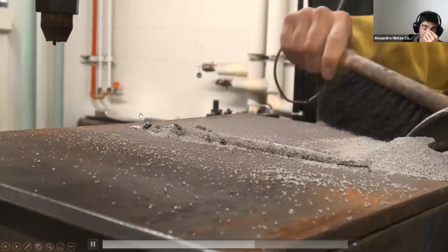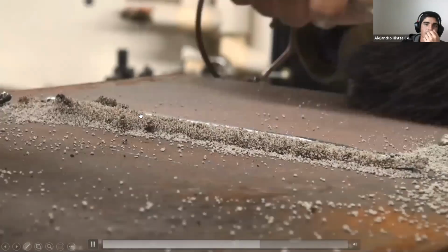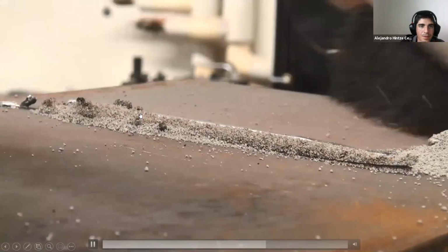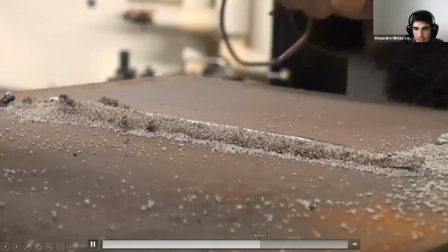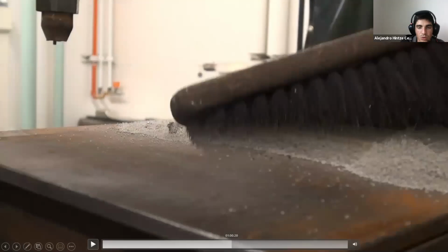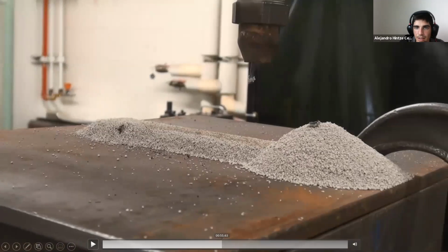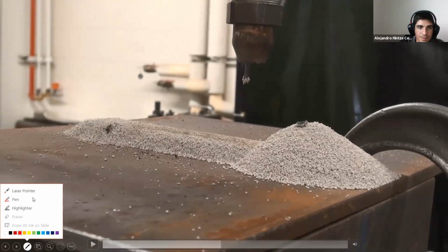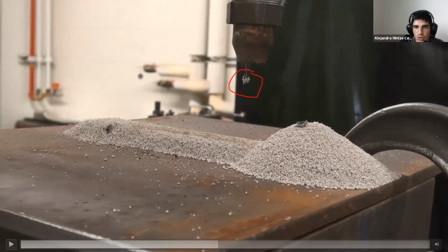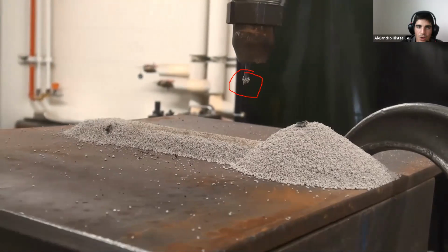Yeah, it's a good practice to cut off the thin wire, and we do it every time. As you can see, when you lift up the wire, and it's a good comment that Wesley made, you'll see that your wire has a lot of flux, right? So this is the part that you want to cut off before doing another weld. You just want to cut off that part and start with brand new wire, if that's what you mean, Wesley.